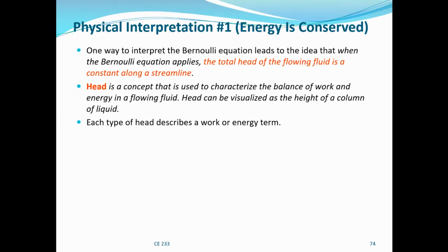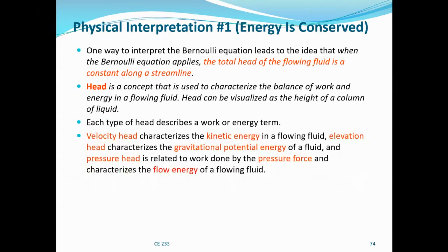The pressure head describes the flow energy, the elevation head describes the potential energy, and the velocity head describes the kinetic energy. The velocity head characterizes kinetic energy, the elevation head characterizes gravitational potential energy, and the pressure head characterizes the work done by pressure force and the flow energy of a flowing fluid.